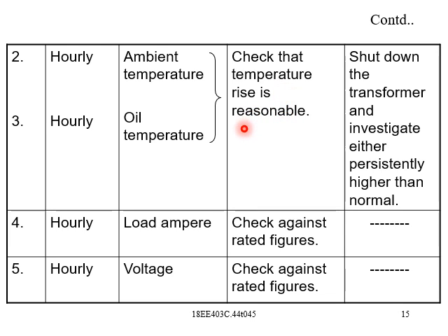Actually, there won't be any decrease in the temperature, it will always be in the range of increasing only, but you need to check for a reasonable rise. And if not, the action to be taken is to shut down the transformer and investigate if it is persistently higher than normal.